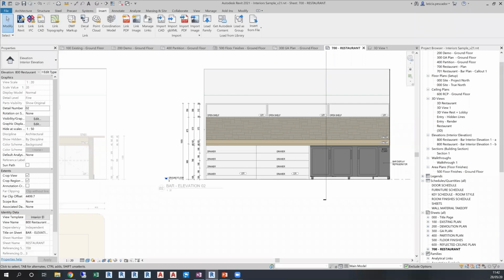When linking 3D CAD files, will they be automatically created in Revit with families? There will be 3D geometry, but they won't behave as Revit families. So you still need to create those families, and if you need to modify them in Revit, that's definitely something that you cannot do with the CAD drawings.